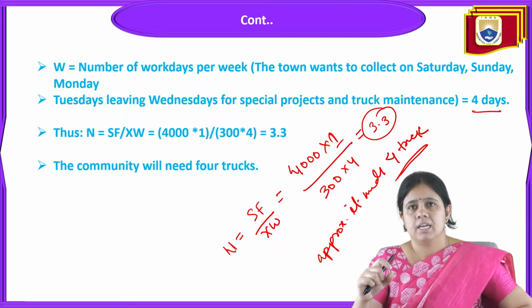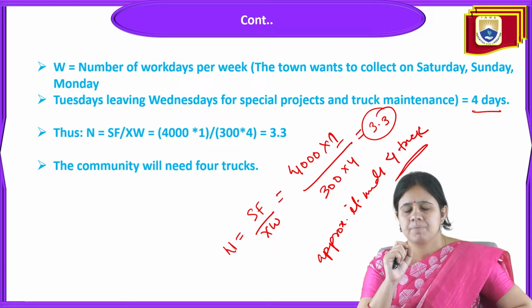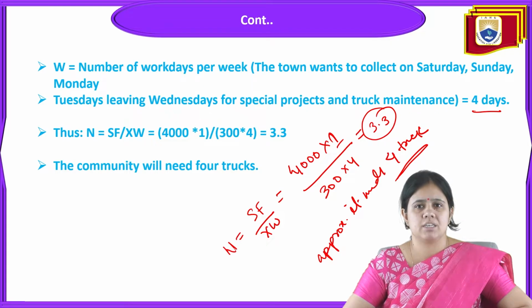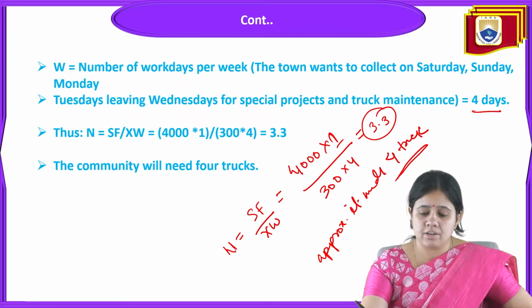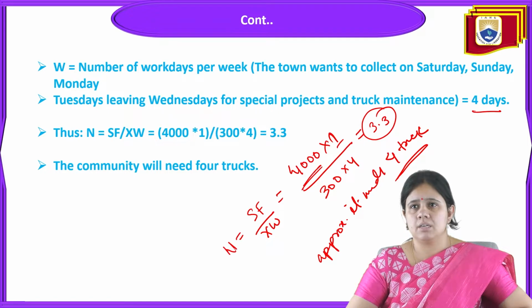a single community. If there are 4,000 persons, we can calculate how much waste is generated. It is half a kg of waste, as already given in the data: a person generates half a kg of waste in a day. If you do this hauled container system operation twice weekly, then 4 trucks are required to serve 4,000 persons in a community. So it has been fixed that this community needs 4 trucks to serve 4,000 persons.